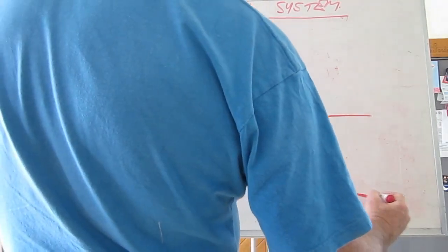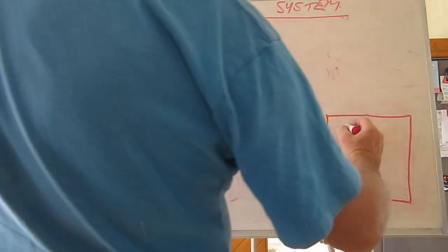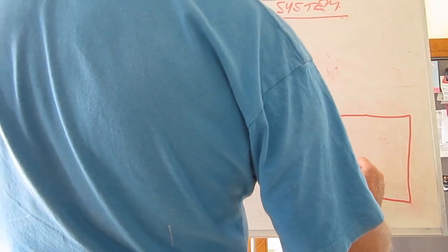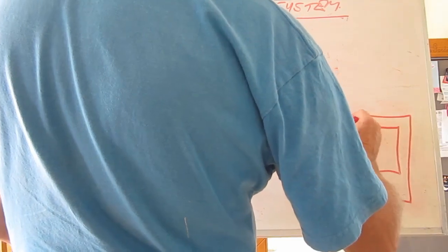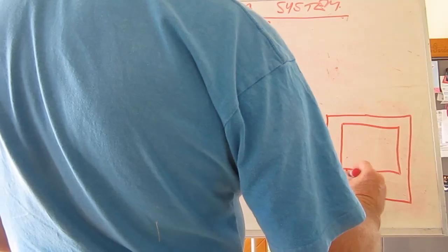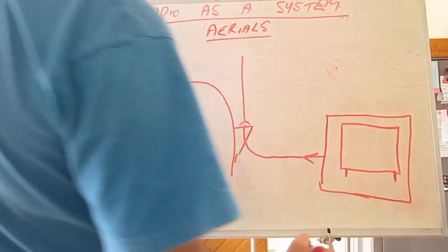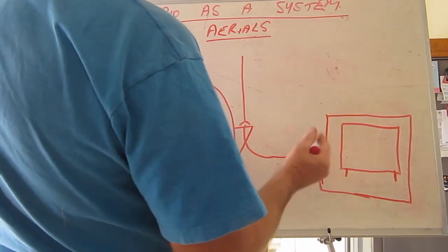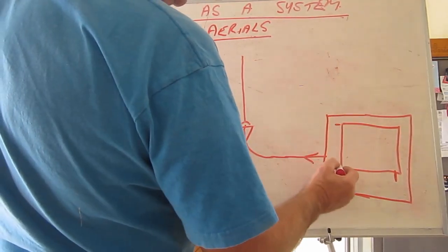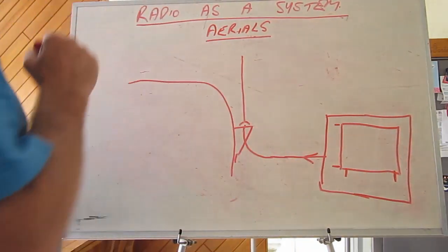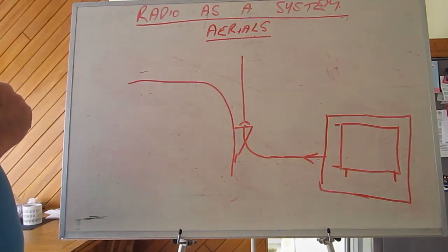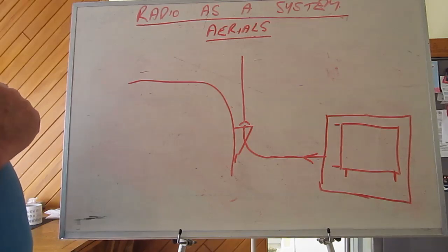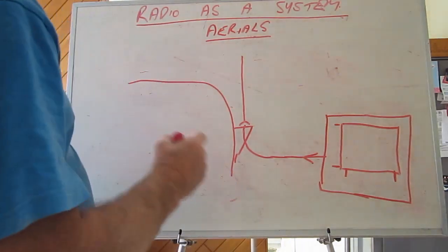So there's no transmitter involved here. It will draw a graph. You sweep the antenna between two frequencies and you set up the scale on the side of the graph to give you an indication of its VSWR as a ratio.